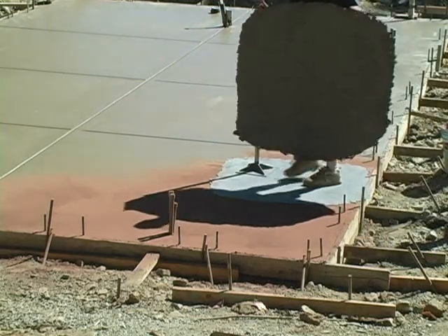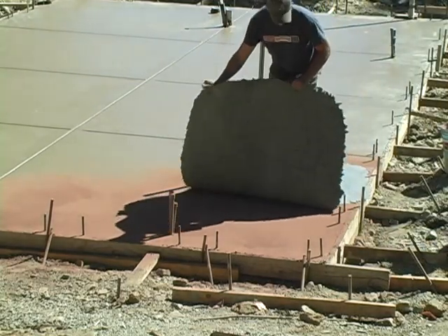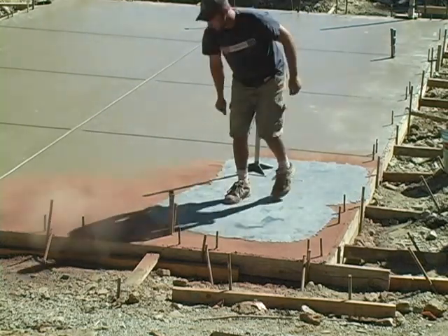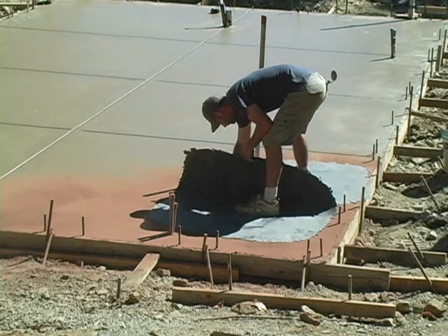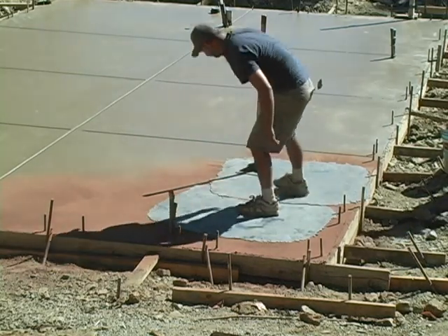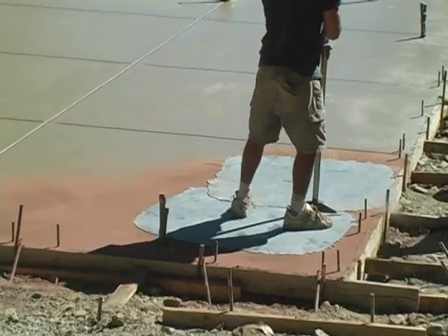Now we'll come and bring the second stamp. We're going to use 2 large stamps for the majority of this building to cover more ground quickly. You see we lay it down over the top so that the new sheet laps over the old sheet, and then we'll reverse that. We'll put the new sheet underneath and continue with the stamping. So what this does is it creates a seamless edge.